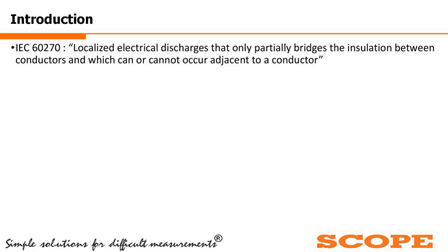So it can happen, it can come and go, it may not happen for 24/7. It is not like the contact resistance or the winding resistance of a transformer where we can go anytime and we will be getting some values. So partial discharge, if it is happening, we have to catch the partial discharge at the right time.